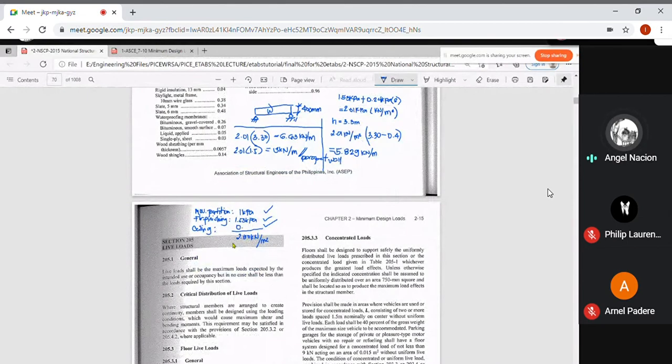So this is what you will do later on when you are designing. All in all, when you add those, 1 plus 1.53 plus 0.48, the total is 3.01. The loading is high. This is approximately 3 kilopascal, but we will assume 2.5 kilopascal. Okay, 3 kilopascal is too high, because it depends on the combination the architect will give later on, and of course the mechanical engineer's equipment that will be used. Alright? Okay? Was this part understood? Any response from the group?